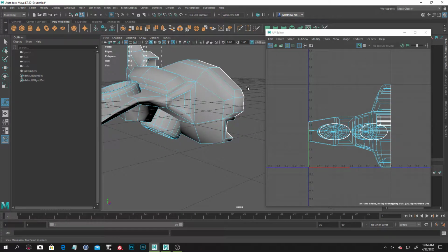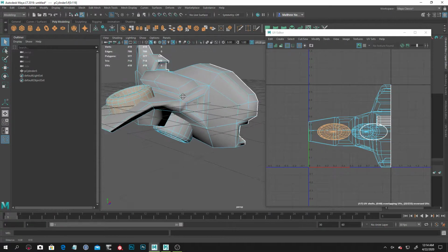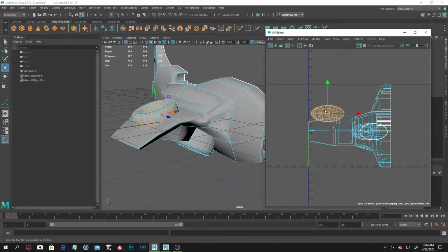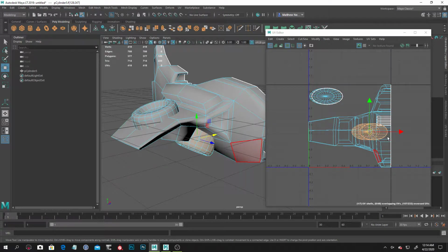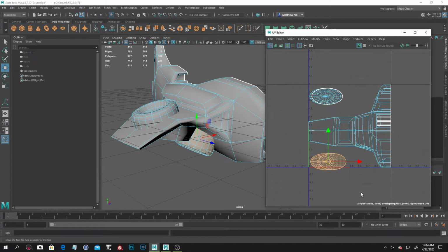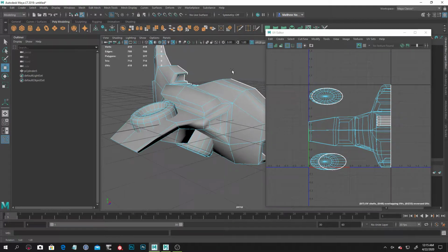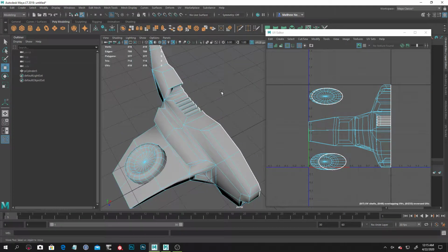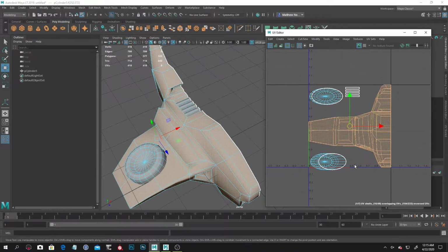So what I mean by that is we've UV'd half the model. If I come in here and grab my face, you can see some of these are already separate because they were separate models. I can move these shells. You'll see as I select those, I have the shells that they UV'd off to the side, right? And again, this might be a little complicated, so don't worry about it. I will have this thing UV'd and ready for you if you just want to paint this. But if you want to give it a shot yourself, you can go for it.